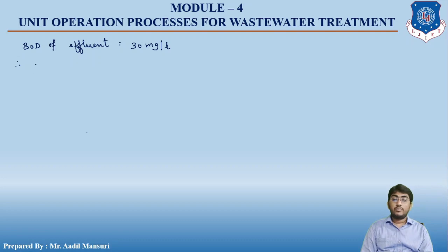Therefore BOD of effluent in total wastewater, right? So this will be equals to 30 milligram per liter into 4.5 MLD.